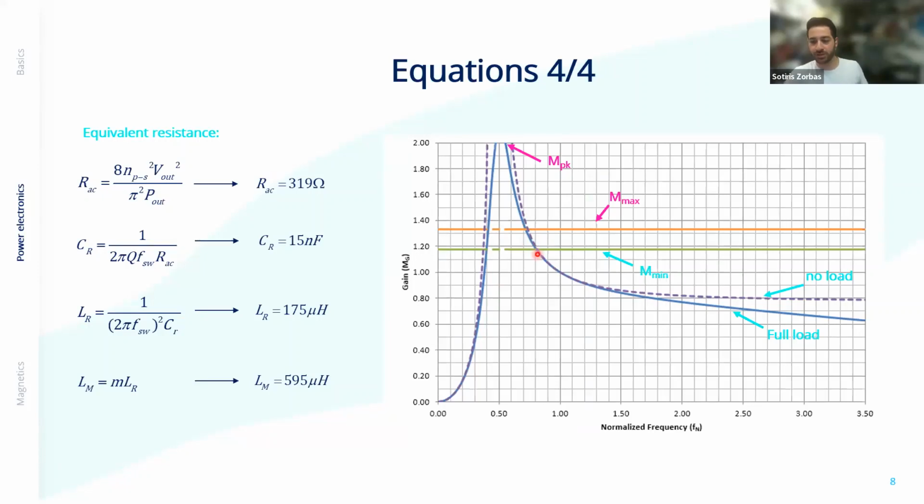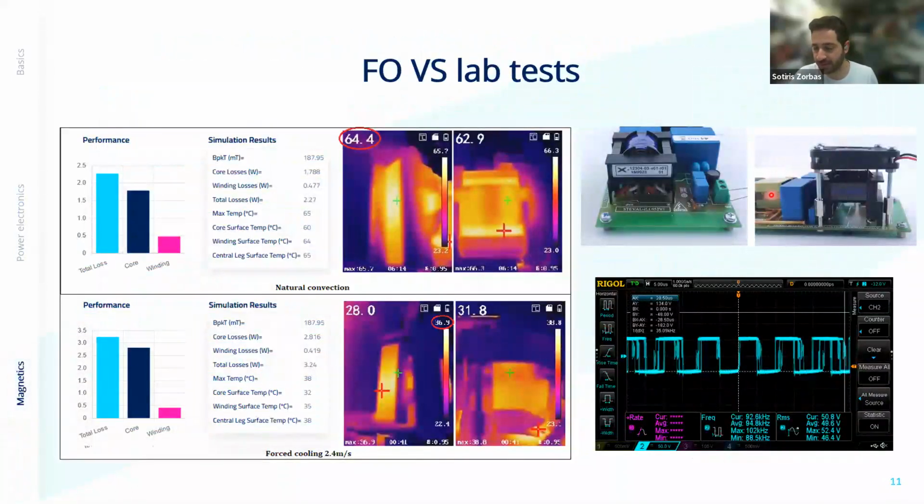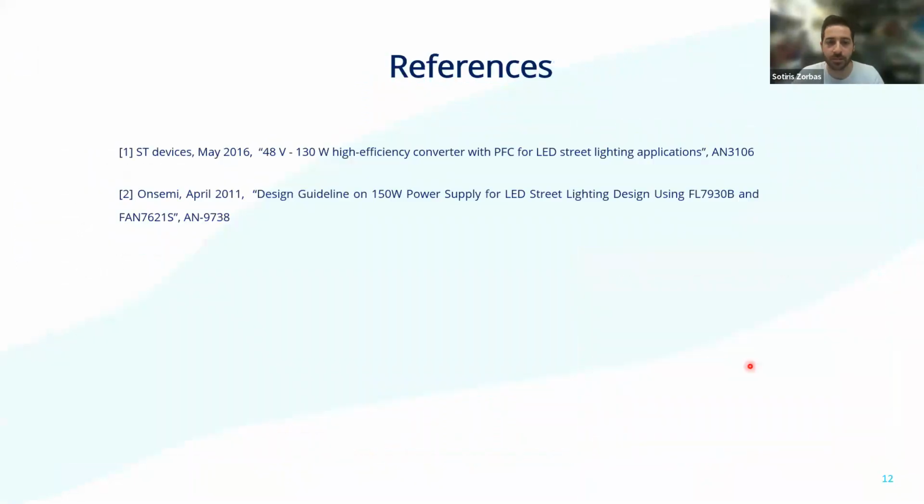This is the low voltage ripple of the PFC stage. But if that voltage was completely fixed from a PSU, this would be completely fixed to 85, 90 kilohertz. As you can see here, it oscillates from 88 to 100 kilohertz. And yep, that's about it.